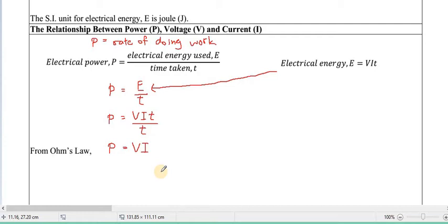This can also be done for resistance. For example, just now I mentioned resistance in a wire. We can also calculate the power of the resistance in the wire. All we need to do is take the voltage drop. Remember yesterday we talked about voltage drop, which is the voltage taken by the internal resistance or the resistance in the wire.